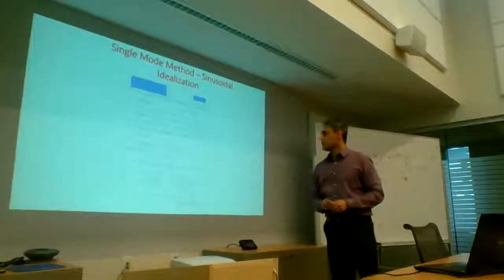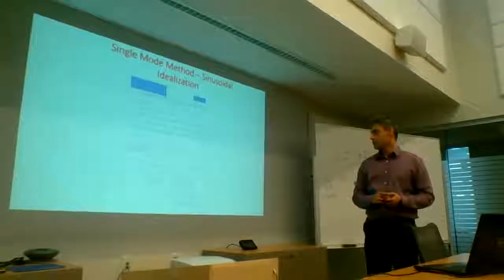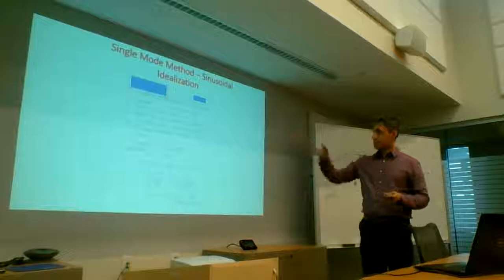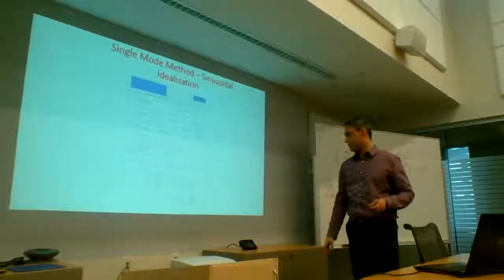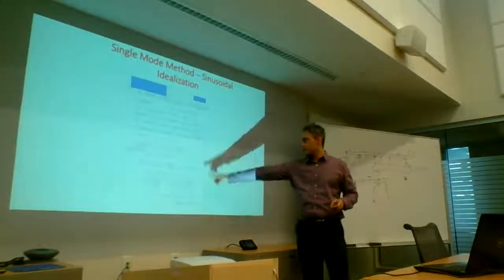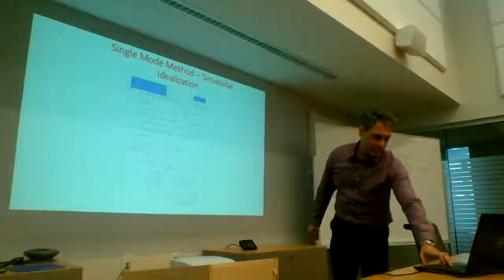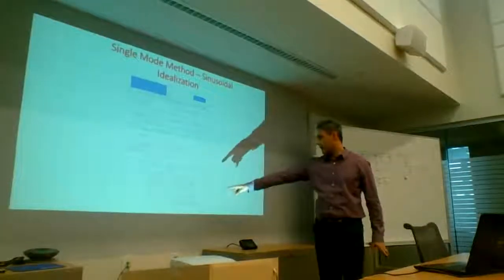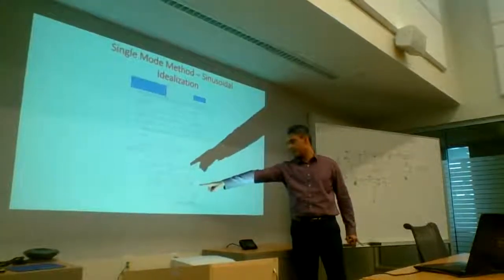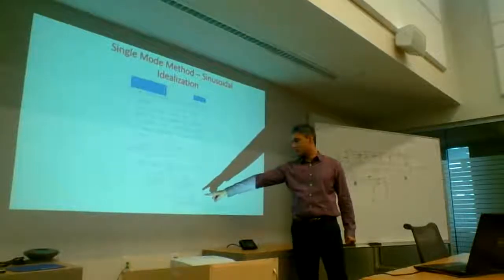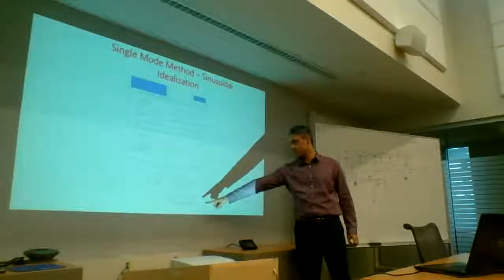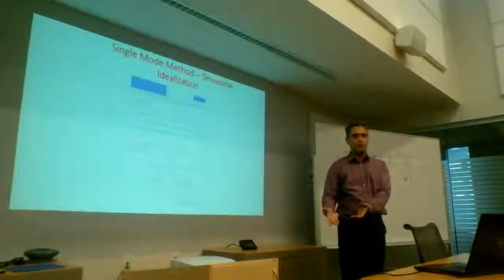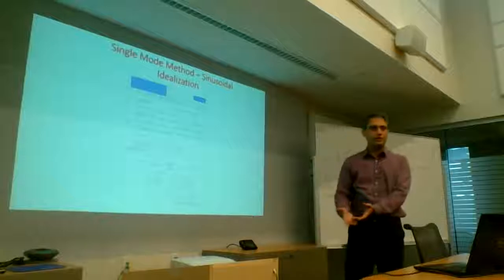So here is a comparison. I've done a comparison with the solved example based on this sinusoidal mode idealization, and you can see here with these expressions that I've given you, with the period and everything, I get 0.384. The spreadsheet is 0.398, and CSI Bridge is 0.406. So 0.38, 0.39, 0.4. Very, very close from the 3 methods.